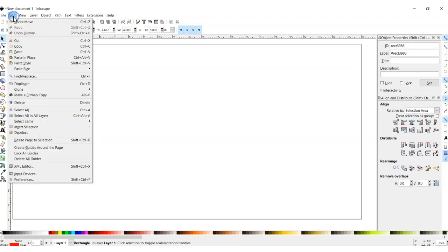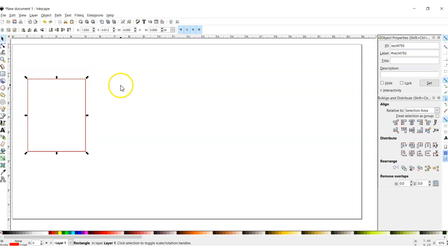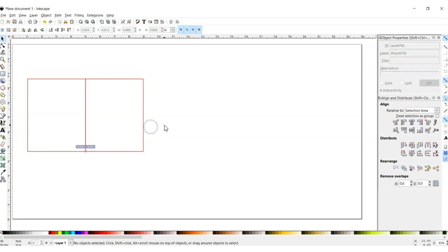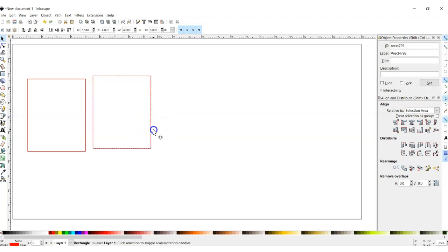Let me show you the edit menu. In the edit menu, there's an option called duplicate, or you can press Control D. So I clicked on that, and what happens is it does a copy and paste, but with 1 button. So now if I move that over, I have another wall. You might see that if you're moving stuff too close to each other, so this shape is very close to the other shape, see how it's kind of snapping to the corner? I want to do that. That's fine. We should let it do that.